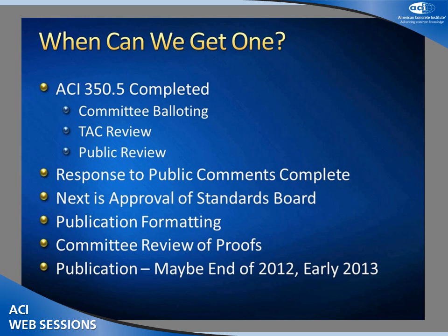And what that will get you is crack control. You'll get smaller cracks, you'll get longer life of your structure, and it will be more resistant to some of those. In terms of repair, it could be done. We don't necessarily specify repair materials, so the materials may have to be the judgment of the engineer in terms of what you want to do in your specification. But the basic principles in terms of process, if you're shotcreting or casting, a form and pour type of repair, many of the provisions could still be worked. It would take some judgment probably to do that.